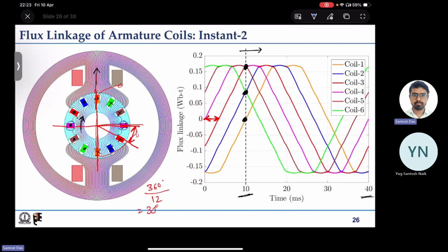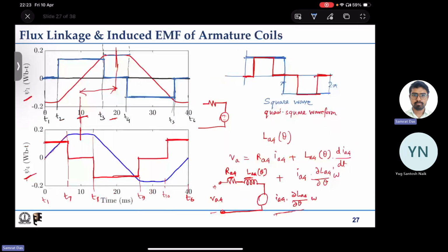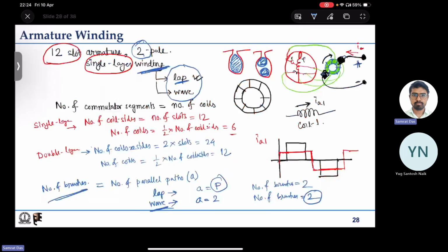The inductance is actually changing, but still, when you are modeling the armature winding, as you have solved for individual cases for your machine parameters, you know that it is typically a constant number. So this LA, whatever is the inductance of this entire coil, is a constant number.